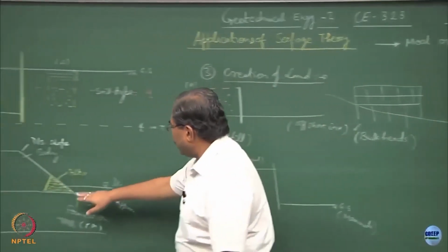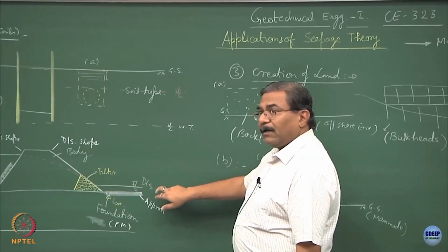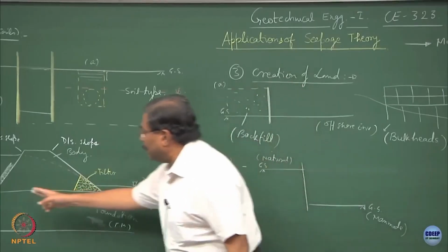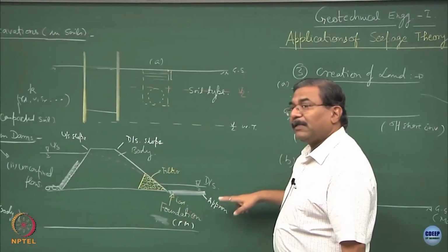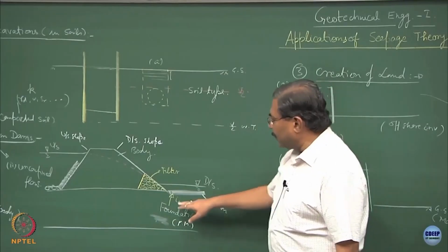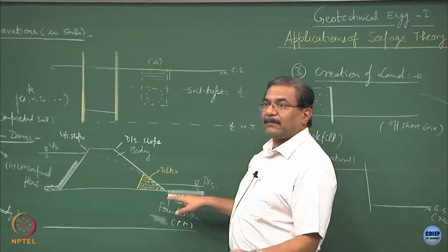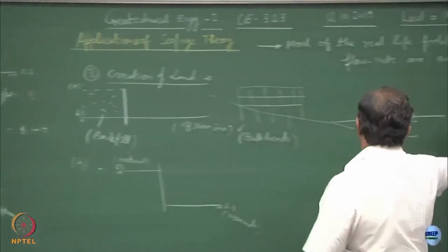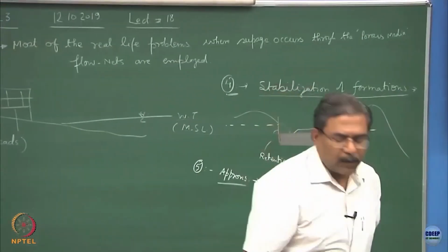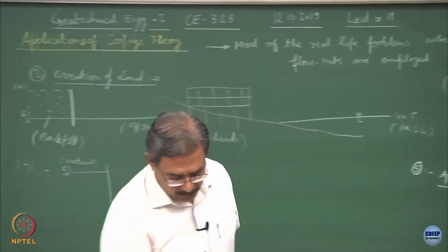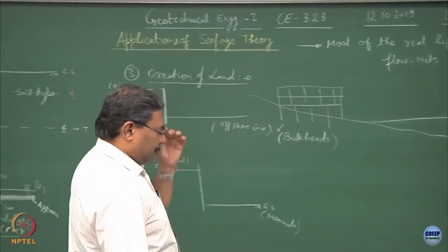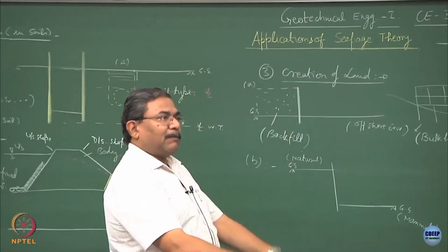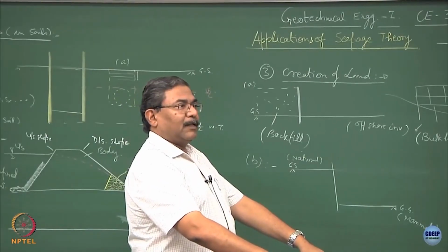So, if I create an apron over here, very soon you will learn, I have elongated the seepage length and hence the hydraulic gradients are going to be less, fine. So, this is also something you can study under the same head, good. What is an apron exactly? Good. See, the normal practice is, suppose I want to suppress something, clear, what should I be doing?